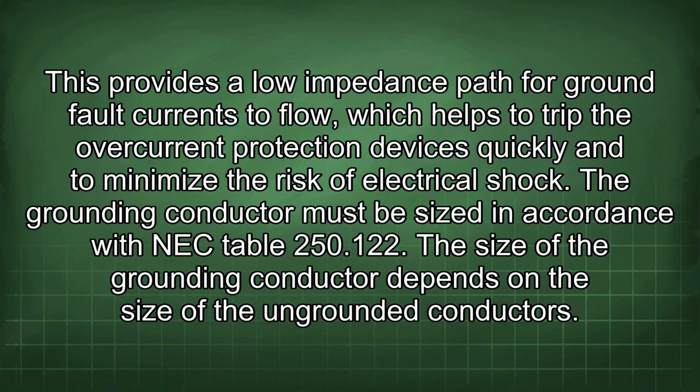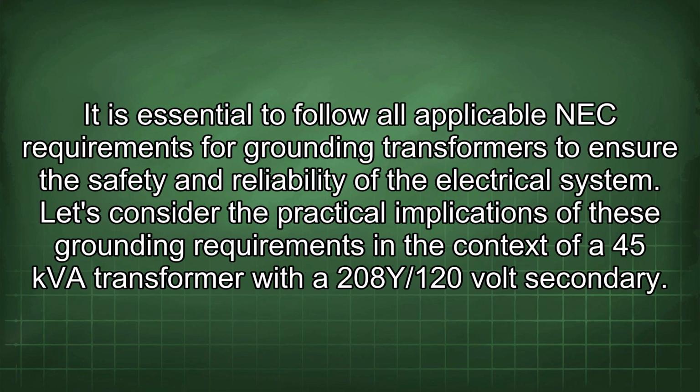The grounding conductor must be sized in accordance with NEC Table 250.122. The size of the grounding conductor depends on the size of the ungrounded conductors. It is essential to follow all applicable NEC requirements for grounding transformers to ensure the safety and reliability of the electrical system.